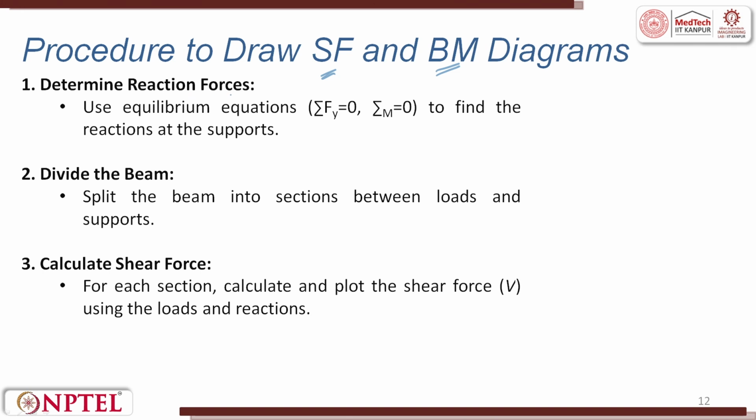Determine the reaction force, that will be step 1. Use the equilibrium equations, summation of Fy equal to 0 and summation of moment equal to 0, to find the reactions at the supports. This is the first step, find out reaction forces.